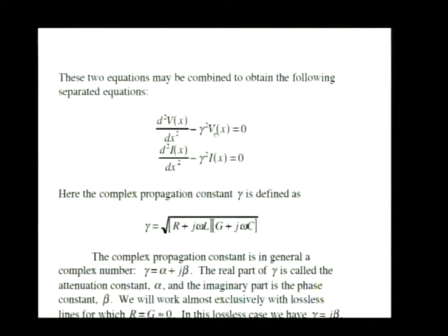Or putting the v of x over onto the same side of the equation with the derivative, this is the form of the equation. You can do the same trick with the second equation. Differentiate it with respect to x. You'll end up with a dv/dx term over on the right-hand side, but the first equation tells us what dv/dx is in terms of I. Plug that first equation in, and you'll end up with an equation that looks just like this. Okay.